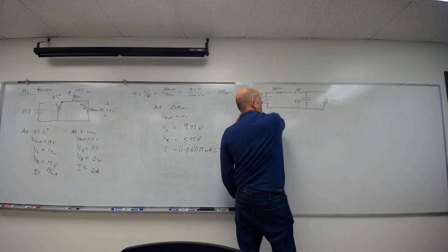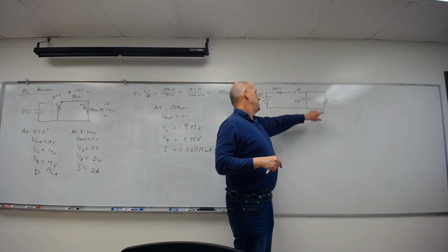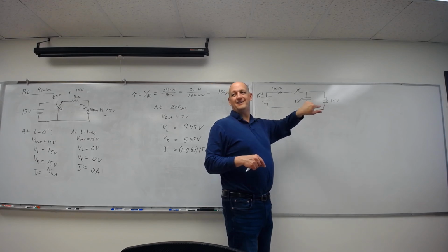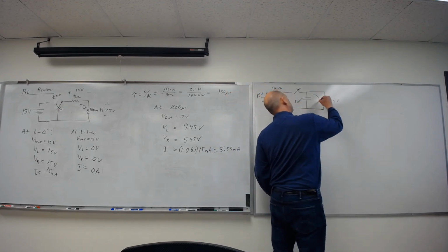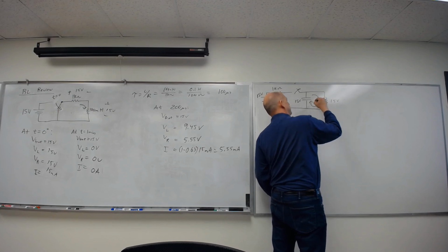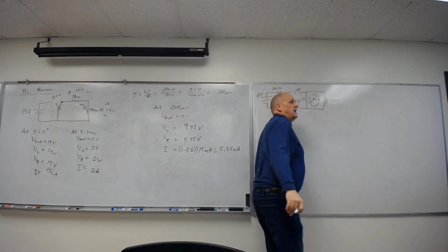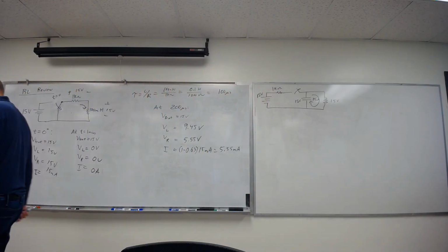So this is all off, and what do I have here? No instant change in current, no instant change of voltage. So my current will go around these two, this current that's being held there, which would have been 15 milliamps the instant I close it. And it'll just sit there.